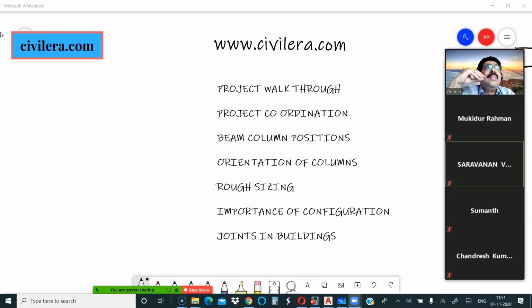You also can have an expansion reason for having a joint in a building. Say you have a 100 meter or 200 meter long building. It's all 2 floors only. Everywhere it is uniformly loaded. Even then you will need a joint sometimes, because as per code 45 meters is what the code allows you. More than that you have to have an expansion joint. You can do temperature load analysis and do away with that joint, but I am not getting into that.